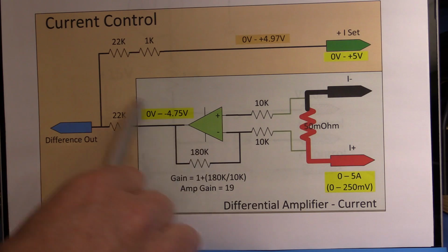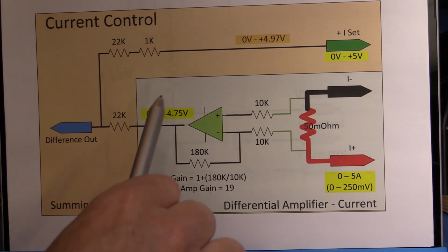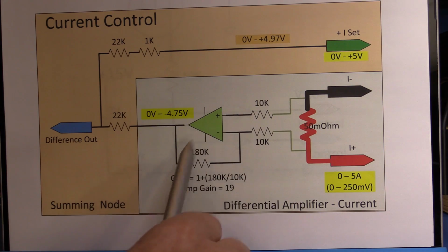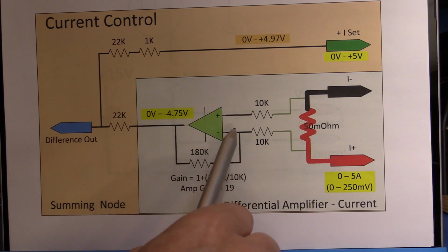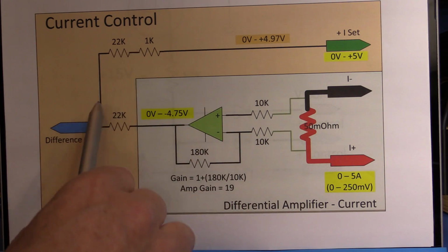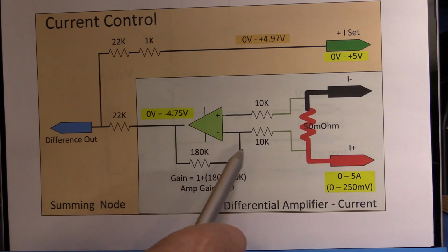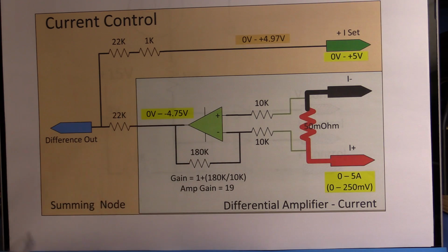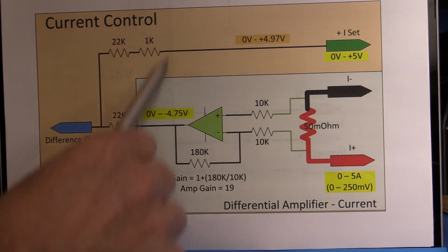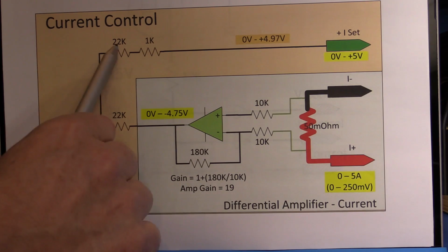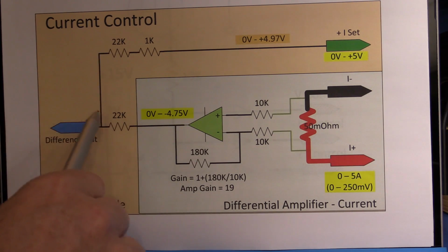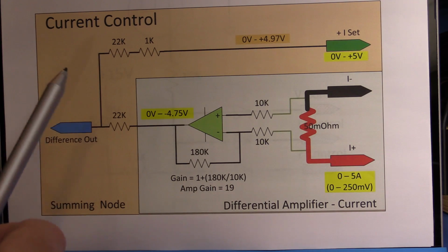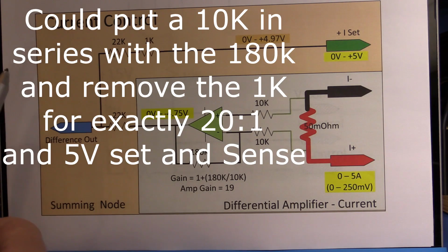What matters is you have them balanced so that the mathematics and the gain and everything else works out correct. And also, if you get them all from the same batch, try to keep them the same. Try to keep the resistor values matching. So if I want 22K here, if this is slightly higher, then this is slightly higher. If they're from the same batch, they're probably still going to be sitting within a certain range of each other. But as I said, you can compensate for that if you need to.